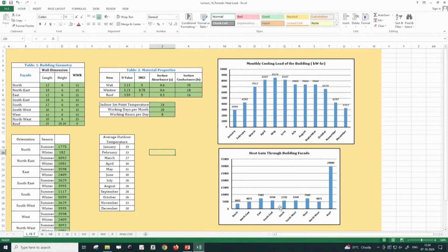So, this is the heat gain through different walls with different facades, and the roof is actually very high, because your roof area is also very high compared to those of 72 and 60 or something, and that was 509. Definitely it will be very high, the roof is exposed, but all other surfaces are almost similar. North is very low compared to the others, east is high, west is also very high in Delhi. So, we have to really take care of the east and west in Delhi. Of course, the roof is always going to be exposed.